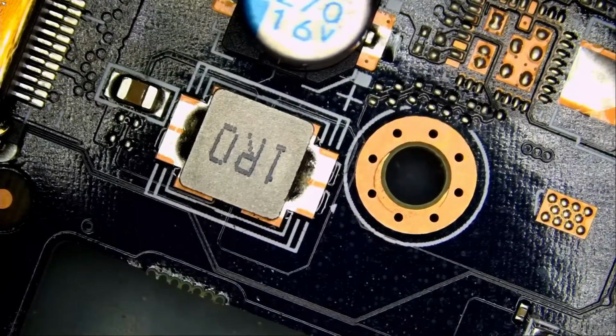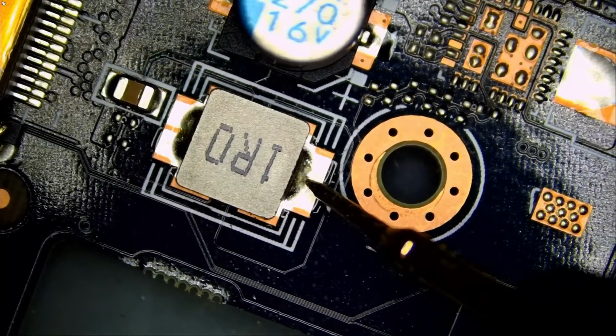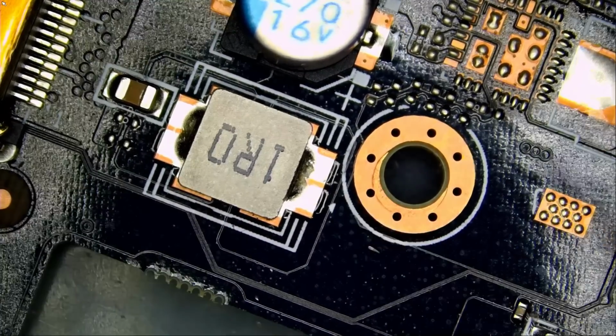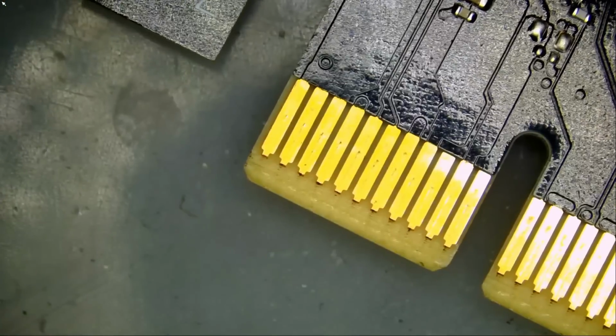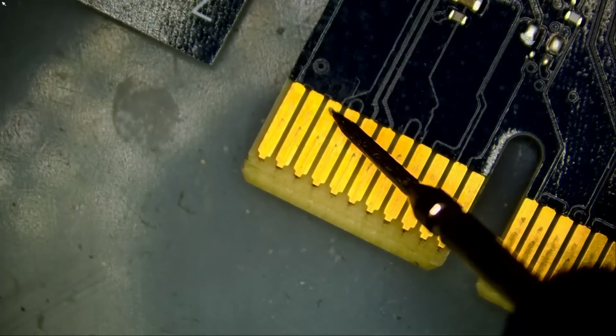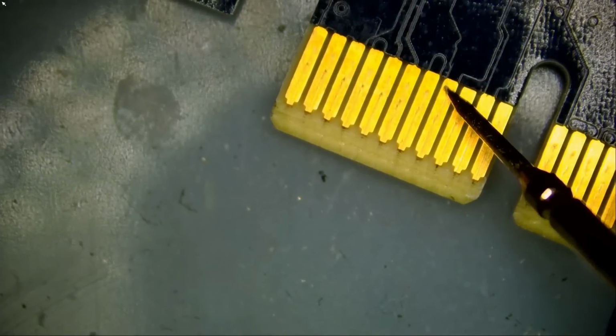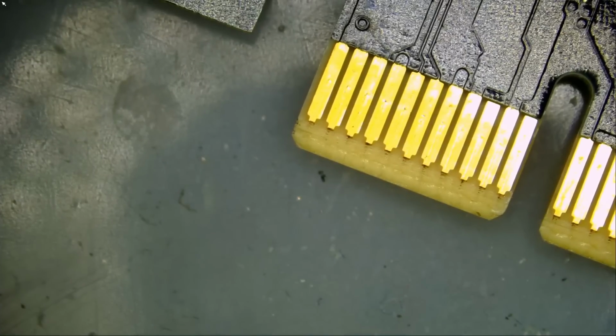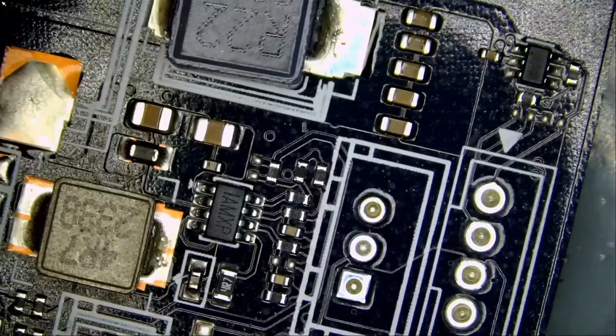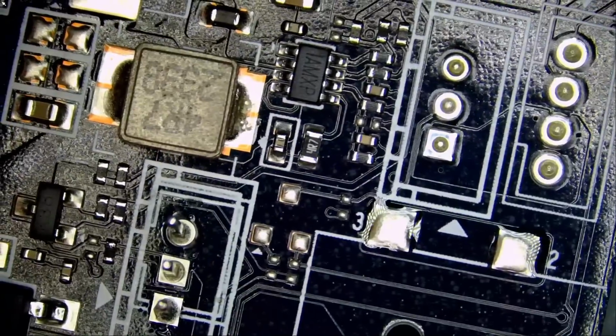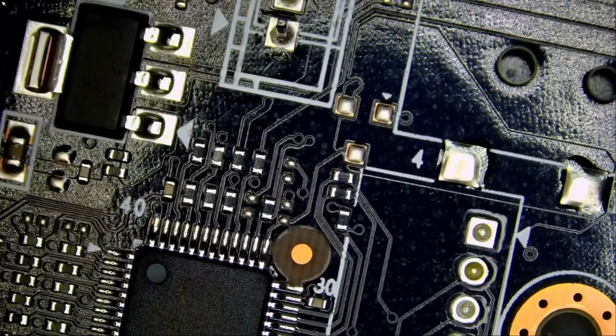And let's measure our PCIe 12V in ohms mode. I'm reading 498 ohms. Measure down here. No short. And measure our 3.3 volt line. We do not have a short. So for the most part, measurements are good. Quick visual inspection so we can find the exact issue for the customer. Otherwise, if we do not find the exact component that made this card fail, we're not going to be able to fix this card.